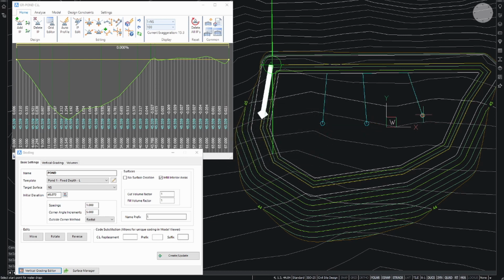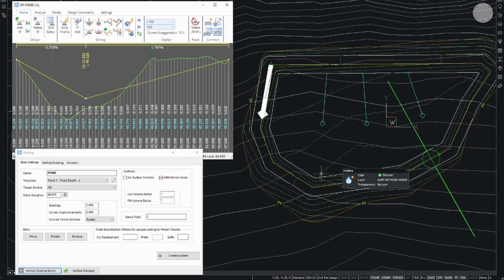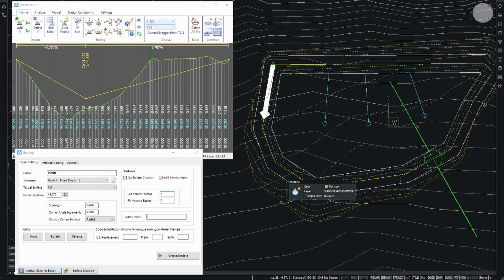You can see that they're currently traveling up the screen towards the top. So if I go and add a new point, and looking at where the green tracker is on plan view, I'll put it here so all the water will drain towards that area. The contours update, and if I hover my mouse again, I can use the quad to update these drops.